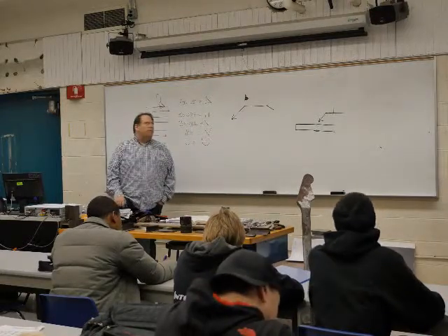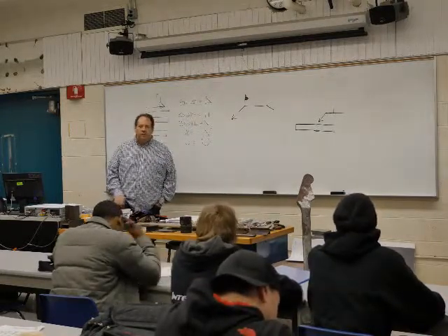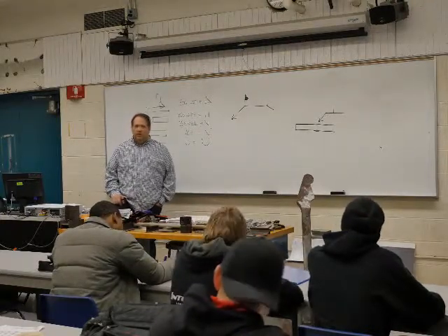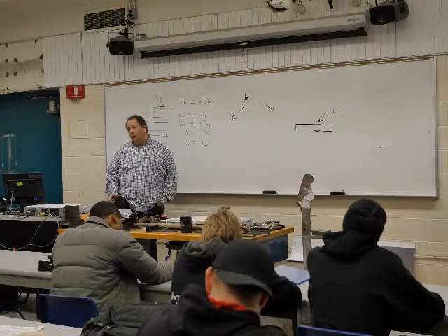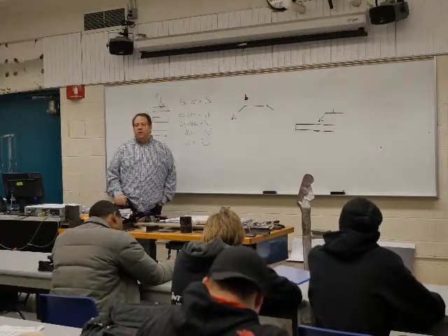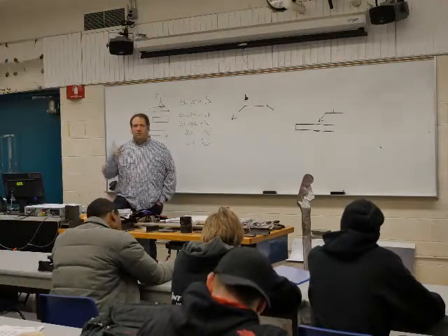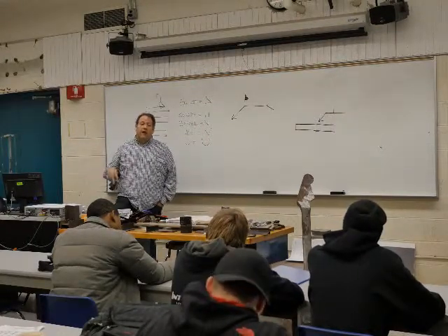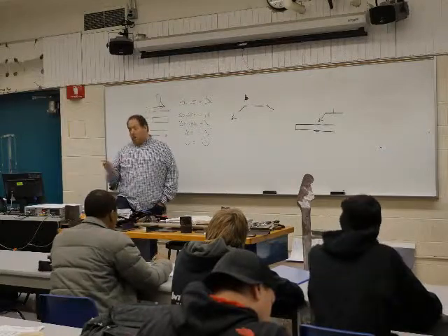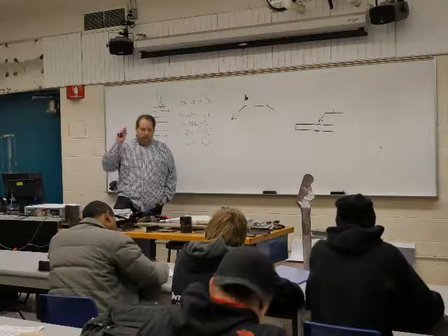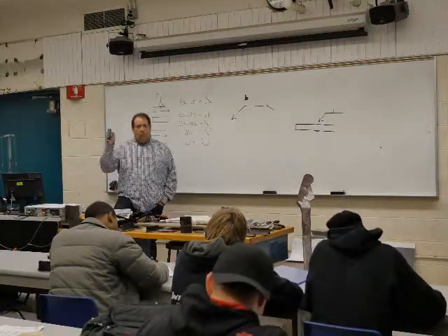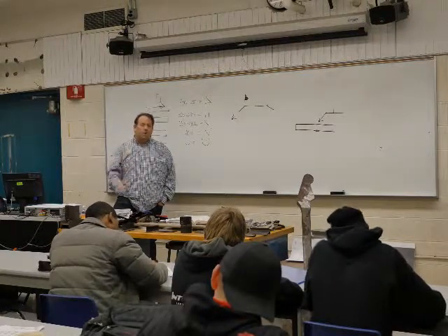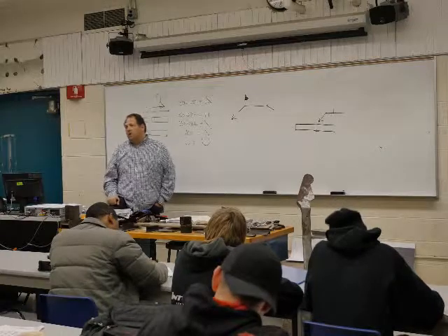Now, what could also happen is maybe there's some dimensional stuff that we're not sure about. Maybe an elevation something needs to be cut first and then welded into place. Maybe they don't know what's going to be on one side of it. Maybe there's some unknown. So they're going to flag it as a field weld, and they're going to say, you know, when you get to the site, this area does need to be welded, but you weld it how it needs to be to make it fit where it's supposed to go. So that could be it.